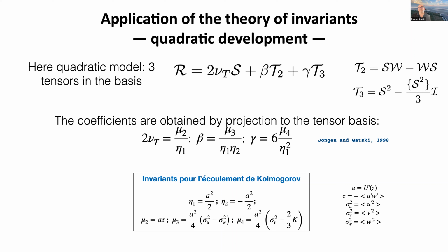Yeah, I think there are different ways to try to generalize this. Because in that case, it's normal that when you have a shear that's 0, your linear approximation doesn't work. Because in that case, you cannot define the strain, which is the problematic part of your representation, right? Yeah, because it's vanishing. Exactly. But in that case, it's like saying that the Jacobian of your velocity is vanishing, but then you can take the second order differential operator of your velocity, which is not supposed to vanish. Okay.